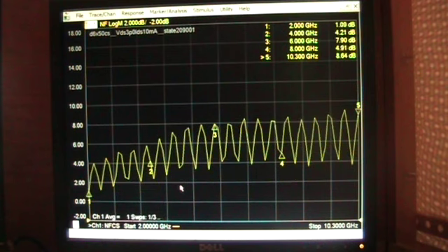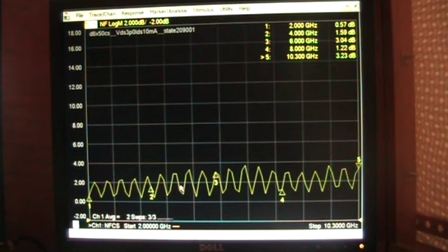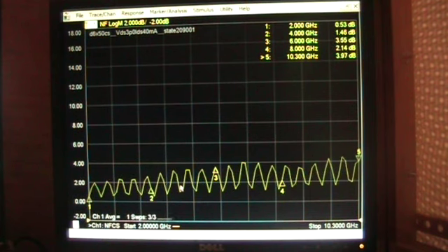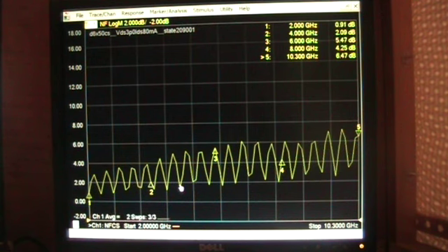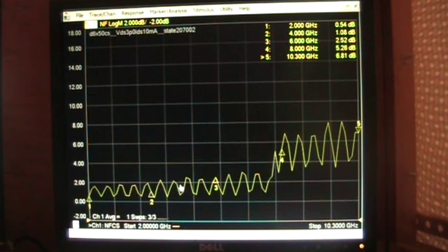Now this code is moving the tuner and then sweeping through the bias conditions and applying a little bit of averaging. So you can see that we spend just a few seconds at each bias point in each state. The order of the measurements is performed to minimize the amount of wear on the mechanical tuner, and the motion of the mechanical tuner also is the slowest element of this measurement. So we would want to do everything we can by moving the tuner as little as possible.